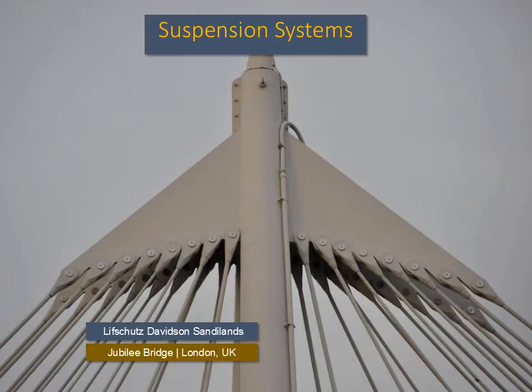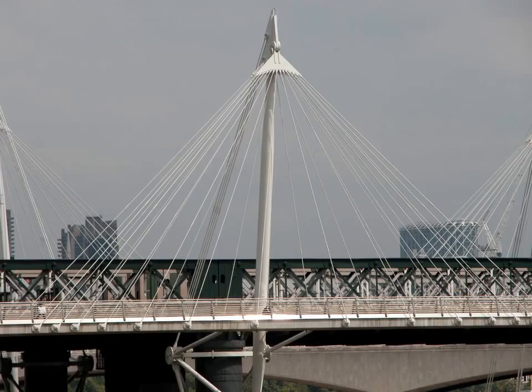If multiple tension elements are connected via clevises, the geometry must be planned carefully to ensure that the plate to which they are attaching has enough steel and adequate distance between the holes that are drilled to accept the pin connections. As can be seen in the design of this bridge, the fan-like geometry of the tension members has resulted in a varied spacing of the supports to the bridge deck. Had their spacing been required to be even, this would have changed the design of the plate at the top of the mast.